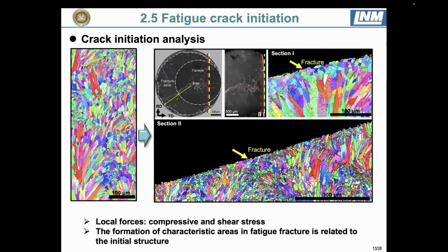In addition, in very high cycle fatigue we also found crack initiation from inside, which demonstrates a fish eye. Along the crack length, we can see some refined grains, and we found some nanograins around the crack length, which are non-uniform.